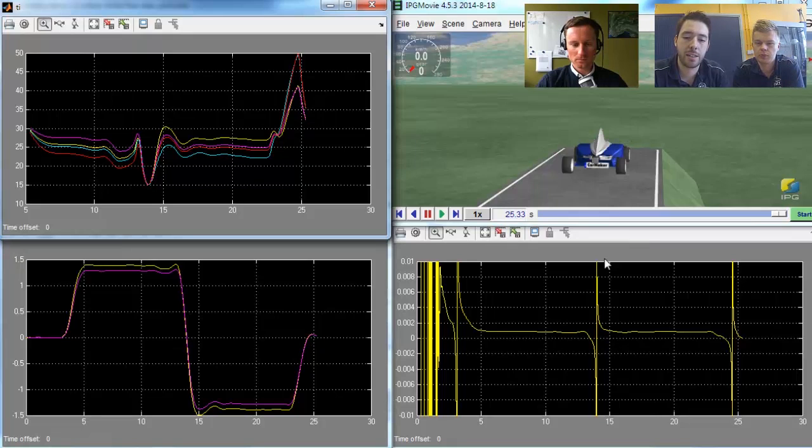Okay. And again, here you can see that during the constant corners it's slightly above 0, which again indicates that the car is slightly understeered. Okay, so for the steady state cornering, we see some understeer happening, but what are the peaks in that signal here? The peaks happen when the driver changes direction. Okay. When the steering wheel is completely straight, the understeer coefficient is not defined and its value goes to infinity. Okay, makes perfect sense here.